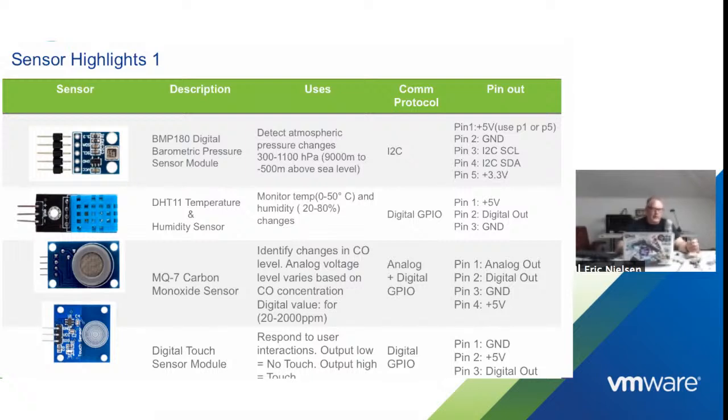I looked at the library to see how they do this, and they pulse it with a clock. Depending on the frequency of the pulses, that's either the data for the temperature or data for the humidity. The Python library or the C library automatically sets up objects or functions you can call to just get the temperature and humidity. So that is the DHT11, very straightforward to wire up. Again, we just put it on any one of the GPIO pins and then power and ground.